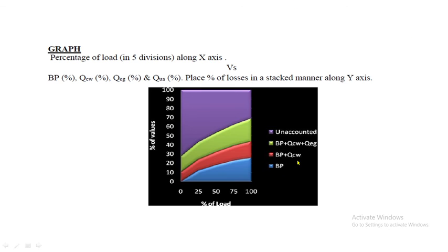Okay, so this is how we have to do the calculations for the remaining experiments, like the performance and heat balance test of a four stroke single cylinder diesel engine by mechanical loading, which we discussed in this session. More or less similar calculations apply for hydraulic, eddy current and electrical loading. The only thing is the input will vary, like in terms of amps for electrical and eddy current. Hydraulic also again in terms of kgs.